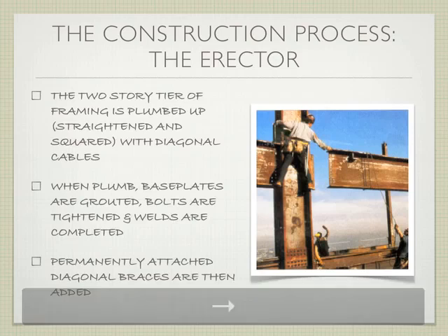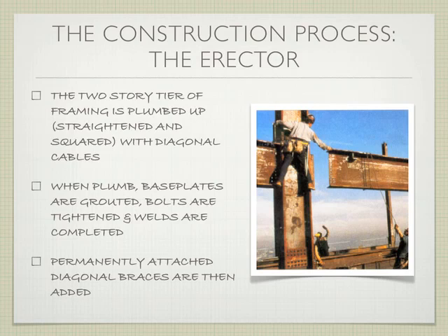So you can start to see how challenging this starts to get, right? When we have these giant pieces, there's all the bolts that are going to have to connect to this plate, right, coming together. So a lot of times they'll use a long cone-shaped piece of steel to help when the crane's coming in. They'll stick it through each of these holes and try to wedge it to keep them roughly together until they can get one of the bolts through. Right? So they're not going to take one of the bolts and risk ruining the threads on the bolts trying to jam it through.